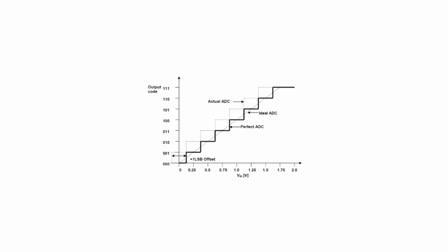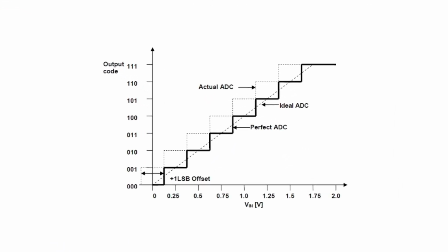Using C code, I'm going to show you how to configure the ADC and any post-processing block to adjust an offset in Texas Instruments C28x DSP. Adjusting an offset means that I will subtract a value from the conversion result corresponding to the DC voltage that has been added.